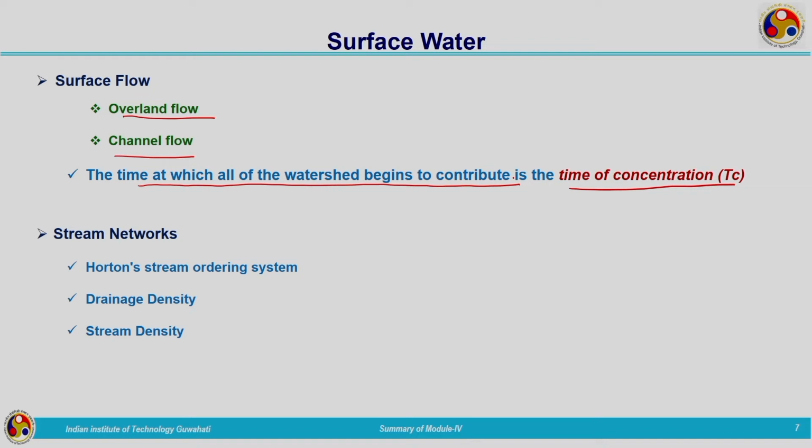So, these terminologies are very important, because whenever we are talking about a catchment with high drainage density, then the efficiency of the catchment to drain off water is high, and easily the water will be drained off to the outlet point. So, when we were discussing the urbanized catchment, we know the peak is very high. Peak is reached earlier because of the well developed drainage systems in the urban areas. So, in that case, drainage density will be high, and hydraulic efficiency will be very high.